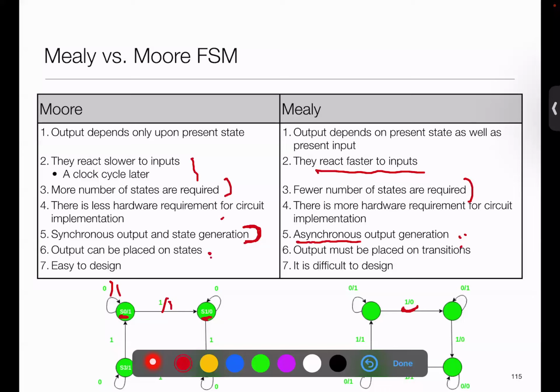We'll see shortly that Moore has a big advantage: it's visually more compact. It's like we are aligning output to state. So we are basically saying that the states reflect some output functionality, whereas in the case of Mealy, it's the transitions which associate with the output. Moore tends to be easier to design and easier to conceptualize, or at least I find it so, but I see many students naturally end up thinking Mealy.